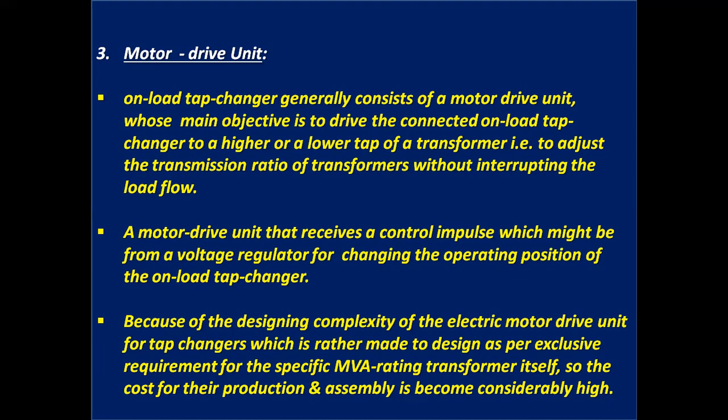The motor drive unit receives a control impulse, which might be from a voltage regulator, for changing the operating position of the on-load tap changer.